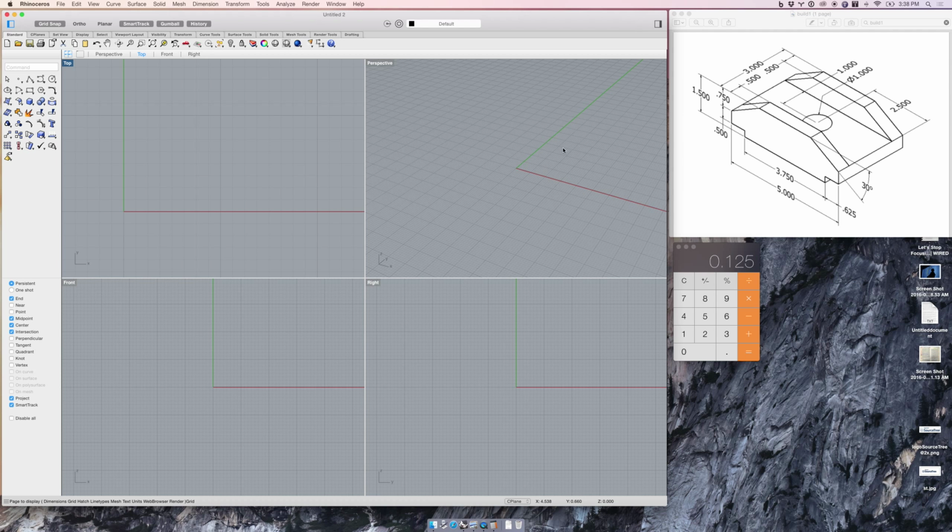Okay. The next thing I want to do is talk about these viewports. Moving around here a little bit. I use a lot of 2 fingers and then holding Shift key to pan. All right, so first thing I'm going to do is build the outline of the shape. It is at its outermost, before I start cutting pieces off of it, 5 inches long, a long ways, and then 3 inches perpendicular to that. So I'm going to make a 5x3 rectangle.